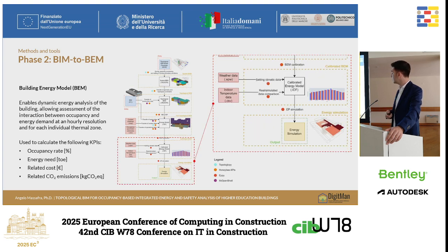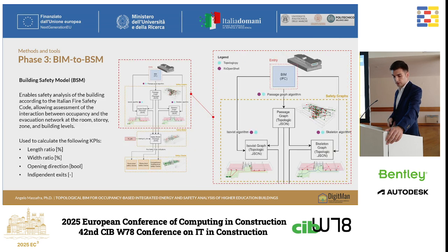And at the end, we calibrate the model with real data, real weather data or real indoor temperature data, and do the simulations to carry out some specific calculations and calculate KPIs related to the occupancy rate of main spaces, the energy need, the related costs, and related CO2 emissions due to this hypothetical energy need within the building. In the last phase, we also automate the conversion to a building safety model.